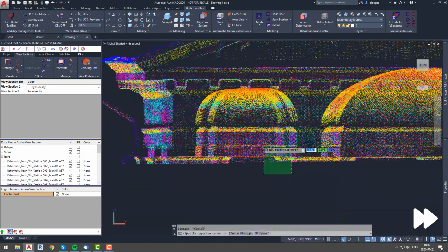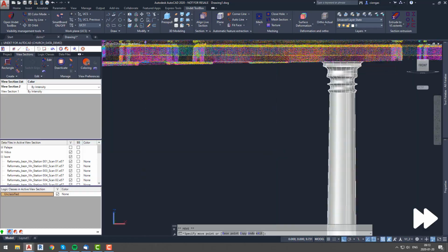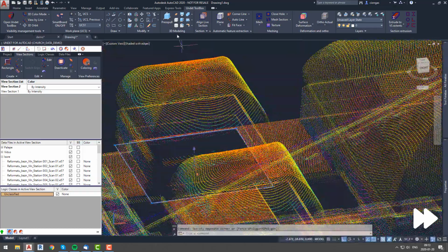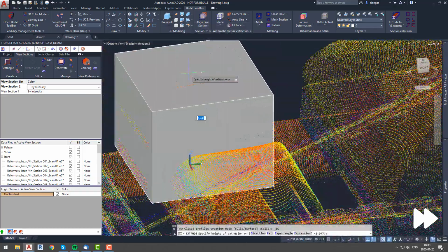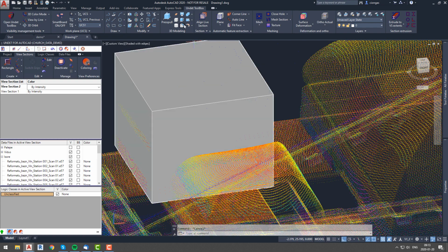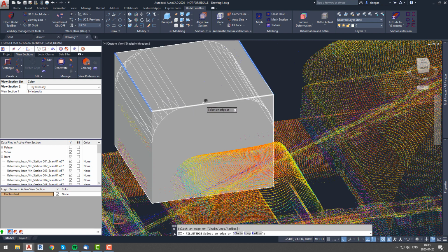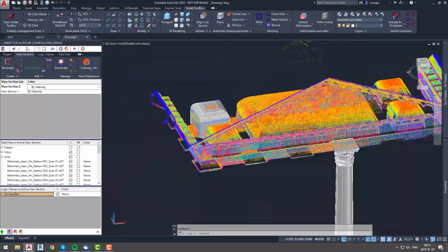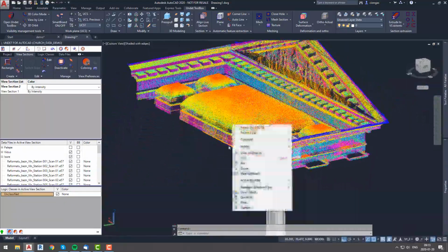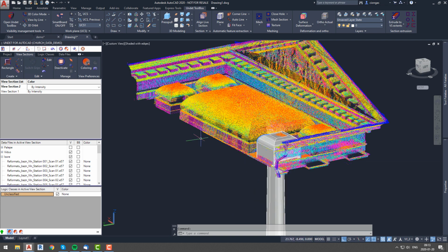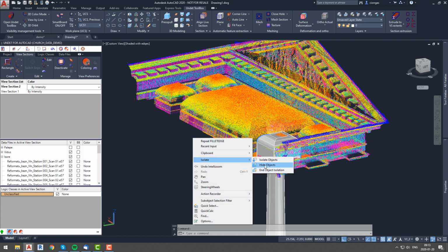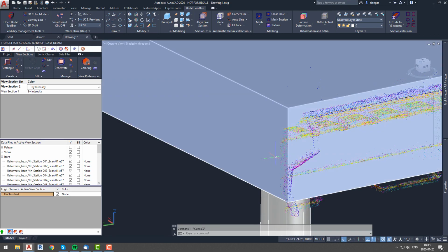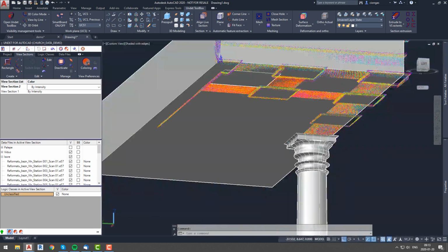We will repeat the same steps as we did with the ceiling element. We will draw a rectangle, lift it to the correct place and extrude it. Now we will use another 3D modeling tool, which is fillet edges. So once we have a clear point cloud view, let's go ahead and fillet those edges to form a vault. Once we have the correct form of a vault, we will subtract this element from our ceiling element, and now we have the first vault in our ceiling. We will go ahead and apply the remaining vaults in the same manner.